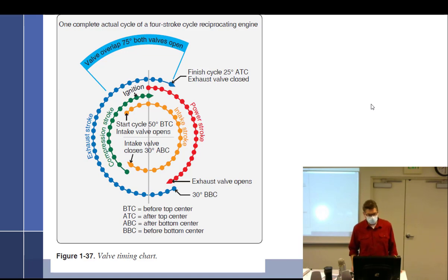All right, so we left off yesterday talking about volumetric efficiency, or lack thereof. We talked about the basic four strokes, which were, what are the four strokes? Intake, compression, power, exhaust. What are the five events? Intake, compression, ignition, power, exhaust.